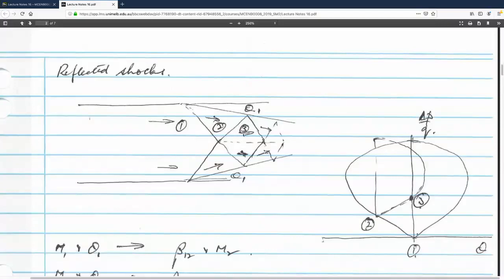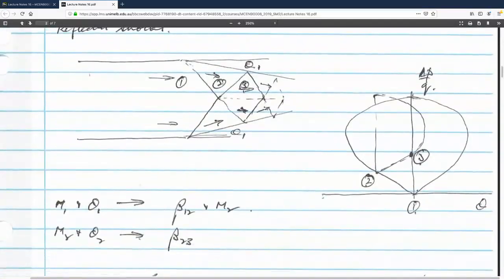So why does the flow have to be horizontal at the center line? Because symmetry would demand it. There are two reasons. One of them is that I've got to match the pressure across this imaginary discontinuity here. Now, in this particular case, there's no discontinuity. In what I'm going to show you in a minute, there will be a discontinuity in velocity and temperature. But in this case, since the flow below the center line is exactly the same as the flow above it, you'll have symmetry here, so whatever you have here, you'll have here. And the only compatible solution is horizontal velocity. And I can easily achieve that by turning this flow from this direction to horizontal through a shock wave.